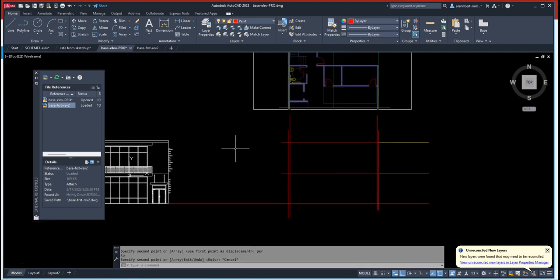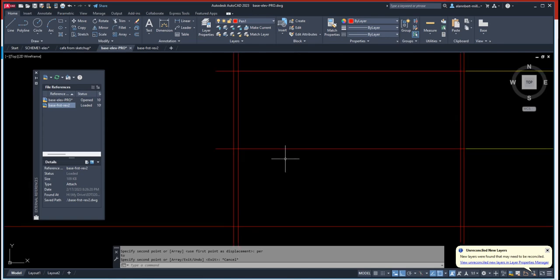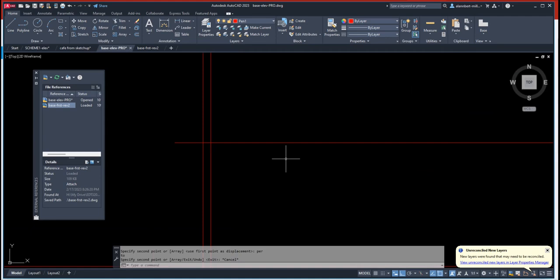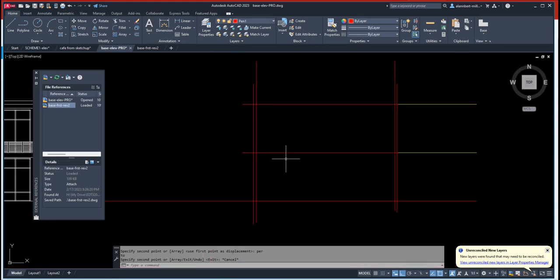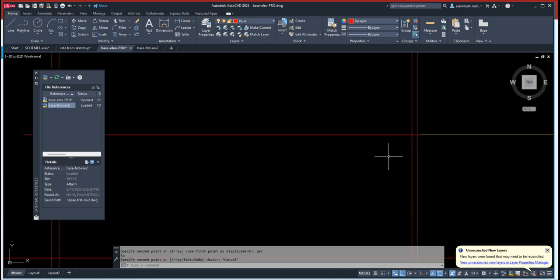Doesn't matter. Now, a lot of people want to show the thickness of the plywood, but from a scaled drawing point of view, that's really too thin to see. But if you want to show it, plywood flooring, you may have a total of 1 inch with a 3/4 inch plywood and maybe a 1/4 inch thick carpet, or if you have laminate, then it's another half an inch or something.